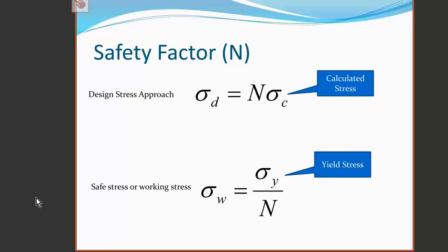Although wood is tested, it is prudent to apply a safety factor such that when we design a structure, we make sure that the stresses are a certain factor below what we consider the maximum allowable, which could be the yield stress or the rupture stress, the tensile strength of the material. For different disciplines in engineering, a safety factor will be applied.